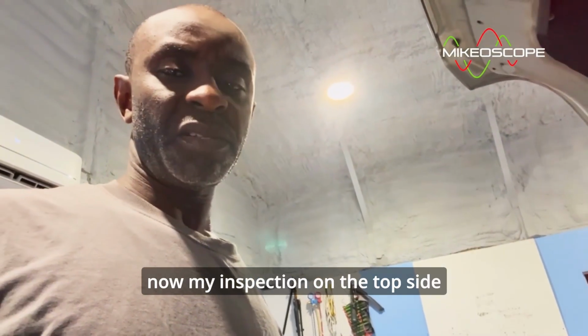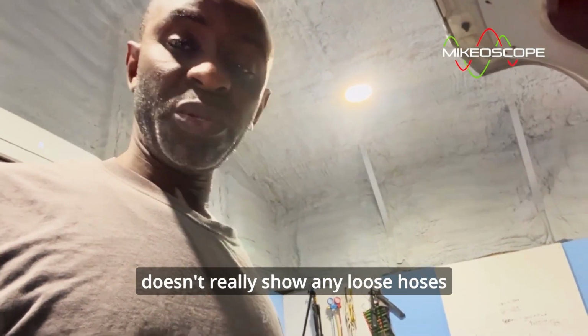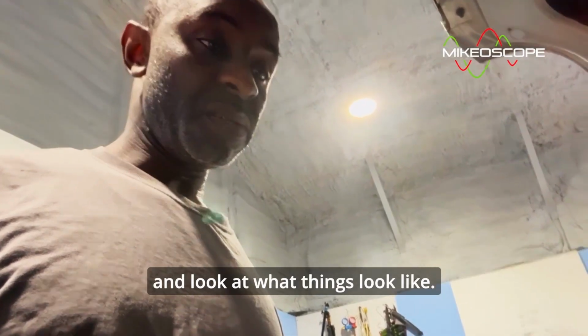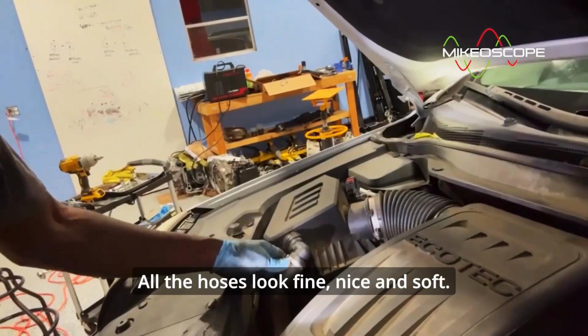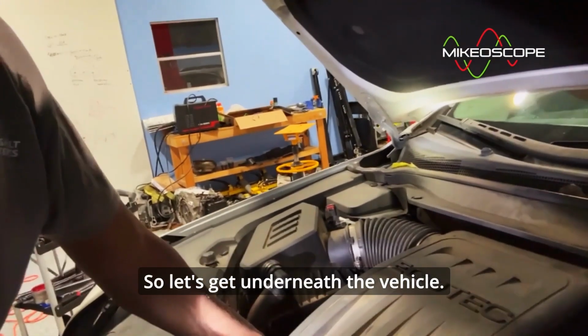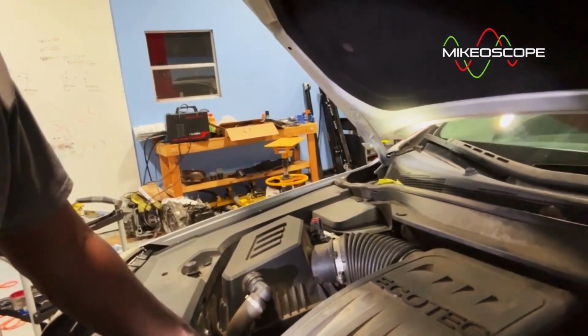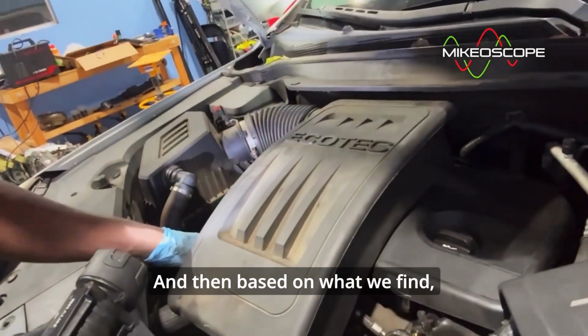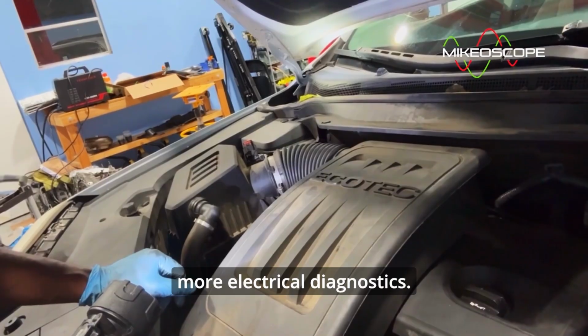my inspection on the top side doesn't really show any loose hoses or any cracks or anything like that. So I'm going to go underneath the vehicle and look at what things look like. So far, everything looks good here. All the hoses look fine, nice and soft. I don't see any cracks or anything. So let's get underneath the vehicle, and then we're going to do more visual inspection there. Based on what we find, we can start doing some more electrical diagnostics.